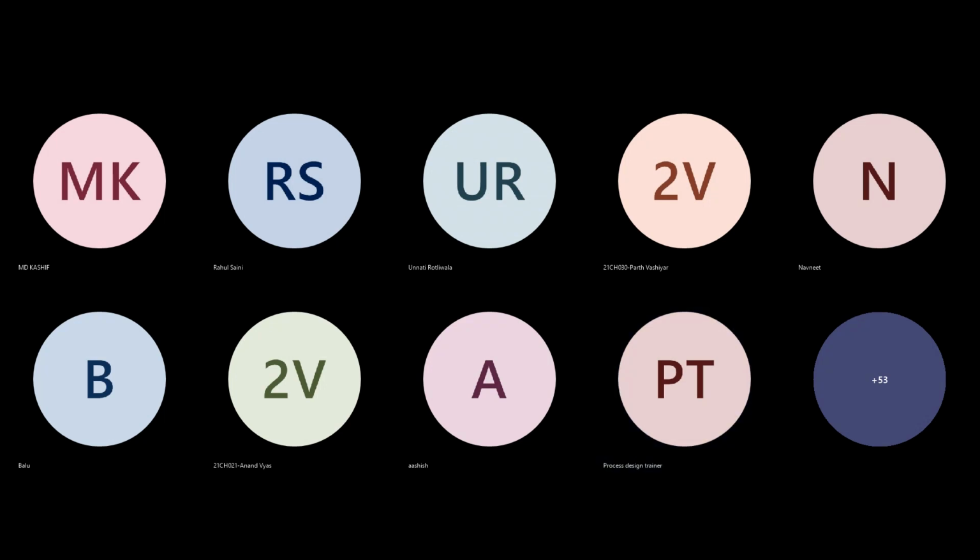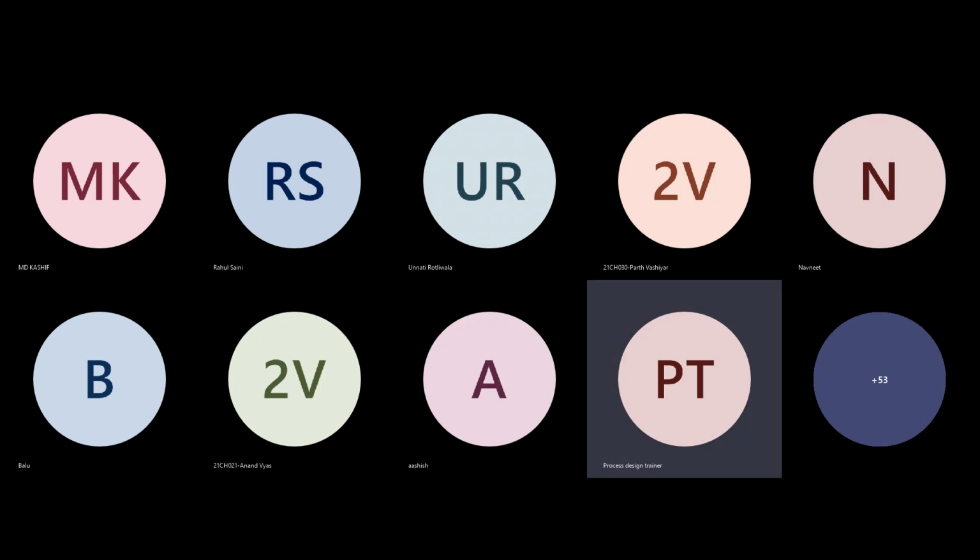Okay. And second point, you are telling that we can take the advantage of the height of the liquid level in the tanks. So what should we consider, low level or high level? I think in my opinion, low level would be preferable, na? We have different types of liquid level in tanks, low level, normal level, or high level. See, with respect to cavitation, suppose your pump is cavitating, then go with the high liquid level. Otherwise, always go for a low liquid level because it will save the volume of the tank.